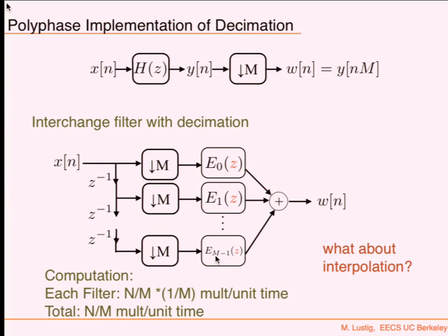It's exciting. Next time, we're going to talk about multi-rate processing in the case where you are going to filter into sub-bands and then downsample, because once you filter something into a narrow band, you can downsample it. And then do operations at this lower rate, or maybe channel operations at a lower rate, and then combine them back into a signal.